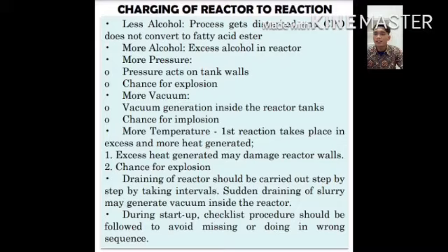Sudden drain of slurry may generate vacuum inside the reactor. During the start-up, a checklist procedure should be followed to avoid missing any step in the sequence. The work-related obstruction was the important look-out by the hazard investigation group.